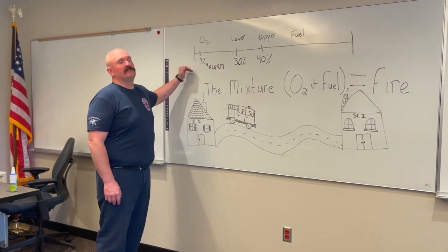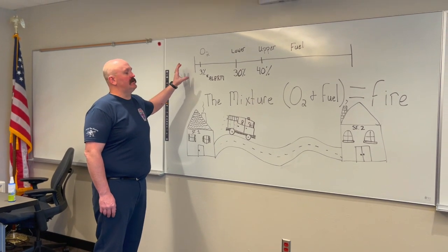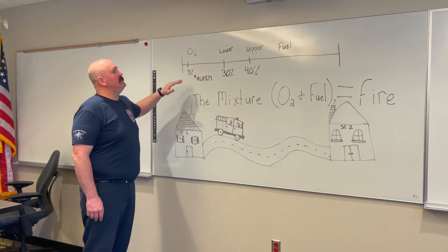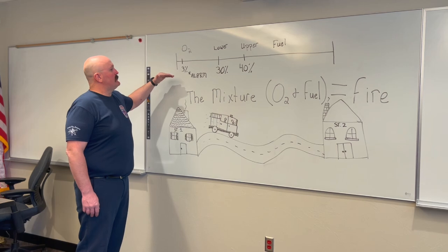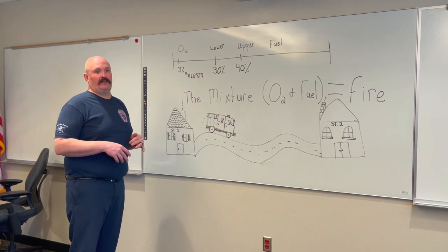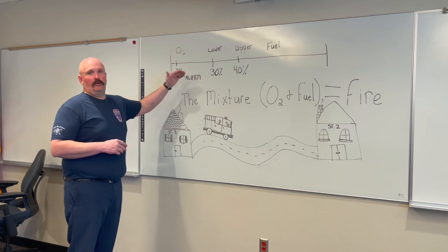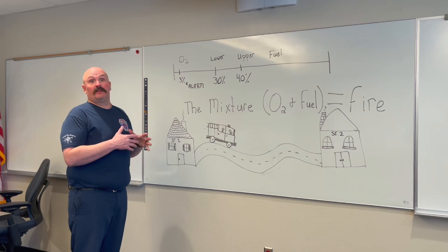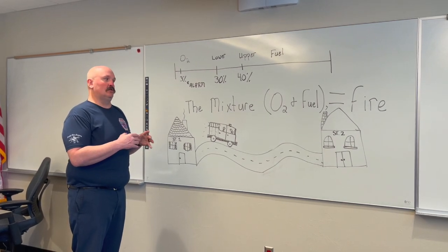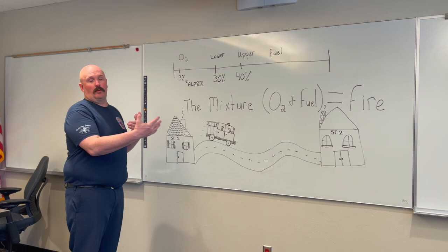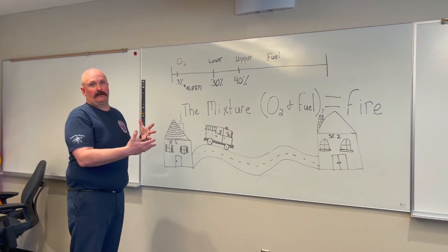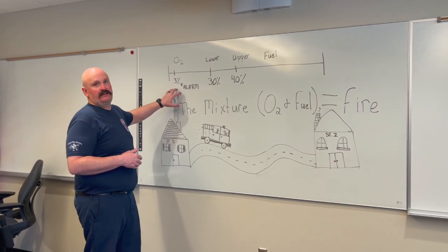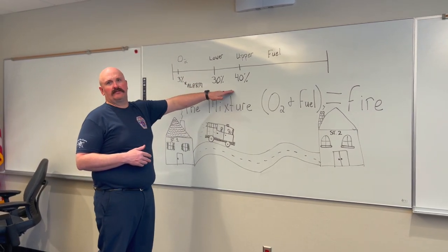The last reading from our CGI is our LEL, which is our flammable or explosive range. That's in a percentage, on a scale. Because there are a lot of various flammable substances, they don't all burn within the same range, but our monitors are calibrated to a specific gas, and based off of that are correction factors. In order to protect ourselves from a wide range of flammable products, our CGIs will generally alarm at 10% towards whatever the flammable range is.